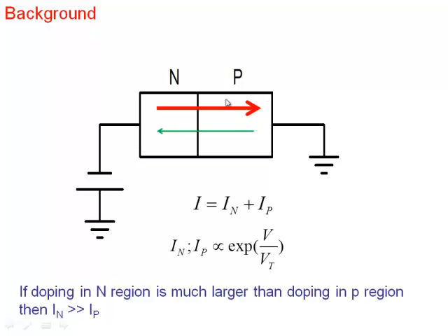And as I said, in a bipolar transistor, if I think of this as an emitter and this as a base, this emitter is heavily doped. That's why I was showing you the doping, 10 to the power 19, and this may be 10 to the power 17, which means that the electron current may be 100 times stronger as compared to the hole current that you see. Okay, 100 times, you can make it even 200, 300 times stronger as compared to the hole current here. So that's the picture that I have for, let's say, emitter-base junction, simply.